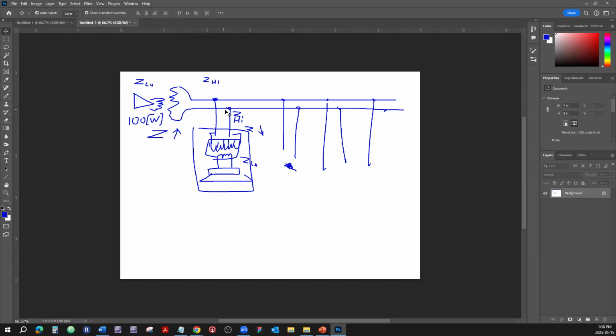And you see the voltage across all of them is the same, so that's why we call it a constant voltage system, distributed audio. Now, in the industry, we have two systems, if I can say that. One is a 70-volt system, and the other one is a 25-volt system. Common systems.